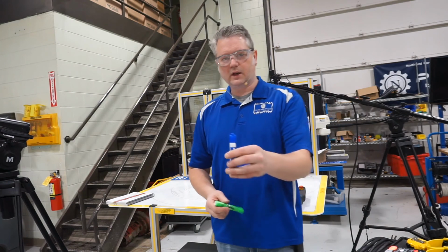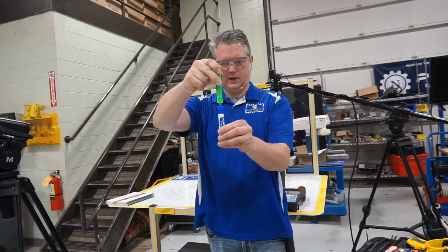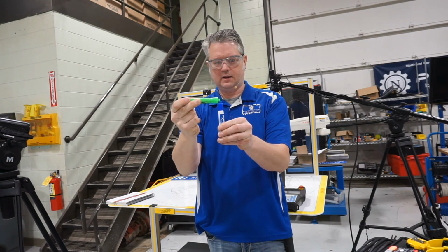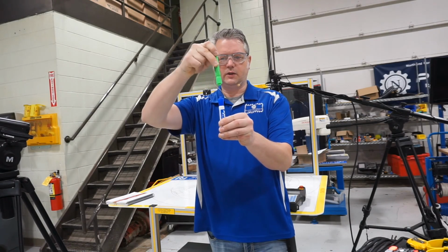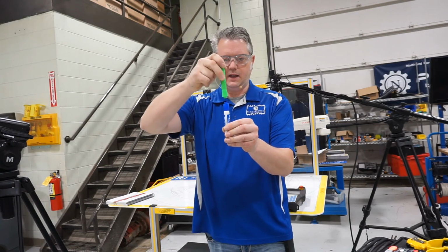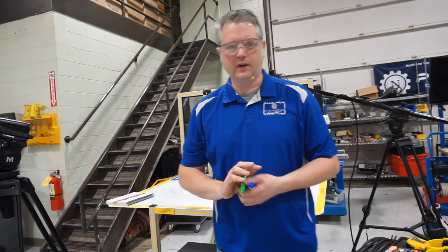The 3-point method we just showed you is a little more time consuming. But the idea, again, was that you have a fixed point here, your robot comes down, you record this point, check. Then you rotate your tooling, come in and record this point. And then finally, you rotate your tooling this direction and come in and record your third point. By recording those 3 points, the software calculates where that end of arm tooling is. And then it's really neat to use these tool frames to jog the robot around. It's a must-have for your programming.